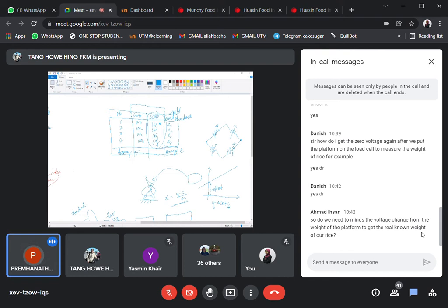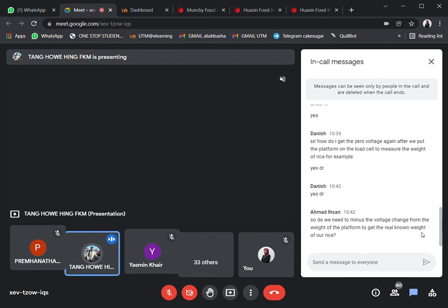Sorry, just to reconfirm, the load cell that we purchased, we already have the Wheatstone bridge, right? Like we just connect it in a Wheatstone way, so we don't need to add some more resistors like that, right? Yeah, no. Actually, if you take a look at the load cell and then the pin out, yeah, something like this. Okay, let me share the screen.